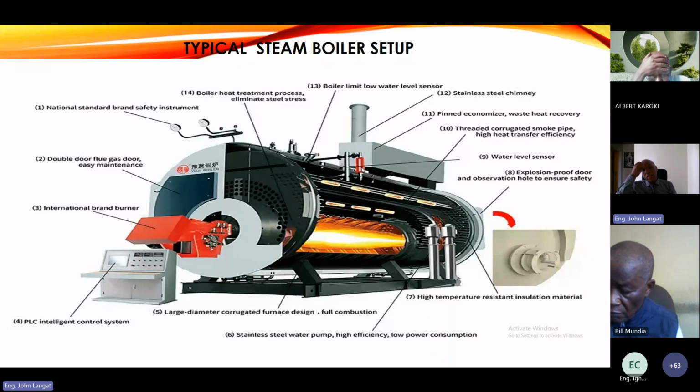The reason why I say the water level always has to be maintained between 3/4 and half is because you need space to accumulate steam. In my experience in the tea sector, when I was a regional engineer in KTDA, boiler operators fear the boiler running without enough water. So they adjust the water level quite high, say above 3/4, and then fire the boiler. But there's not enough space to accumulate steam. So you keep stoking the boiler, feeding firewood, and you're not generating enough pressure to fire your process. You end up utilizing a lot of firewood or fuel while generating very little pressure.